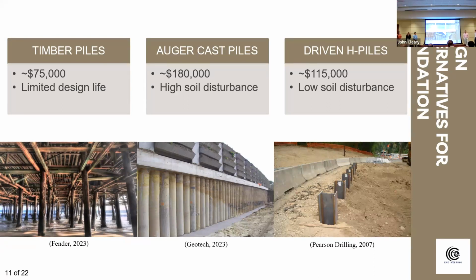Do you have any freeboard requirements above that? So the reason we chose 10 feet was that 5 feet would get us out of that flood level, but it would still keep some of our exposed material in the flood level. So the 10 feet got us out of that, where no exposed material would be in that flood zone. Okay, and what kind of scour analysis did you do below the bridge for those velocities? We just did that using the HEC-RAS software.